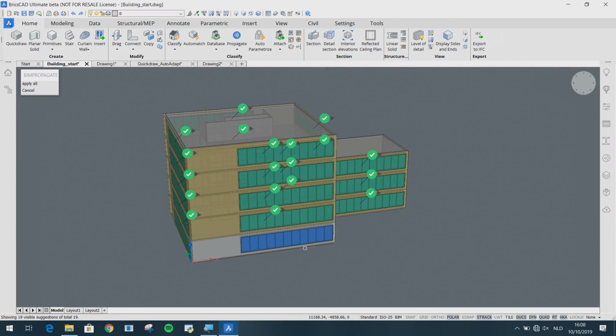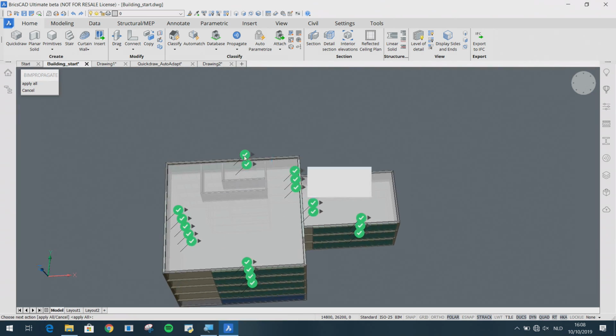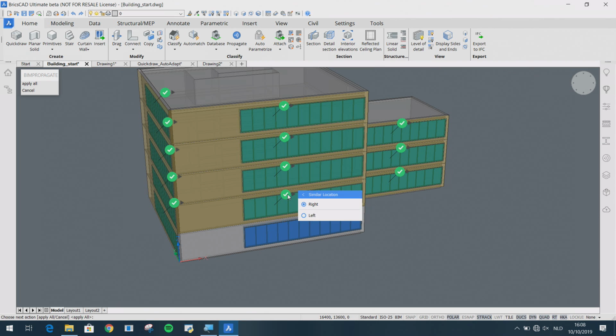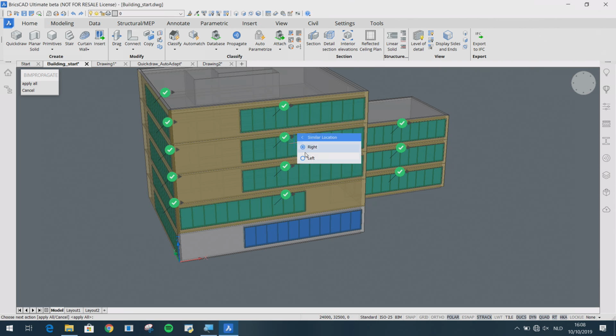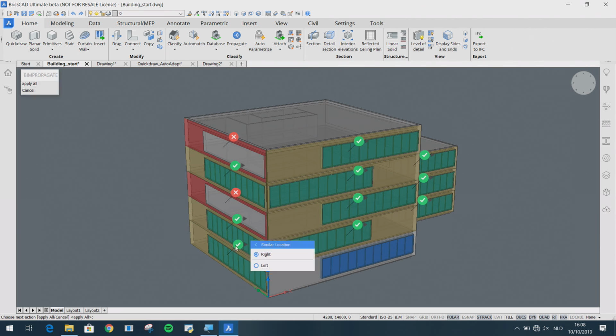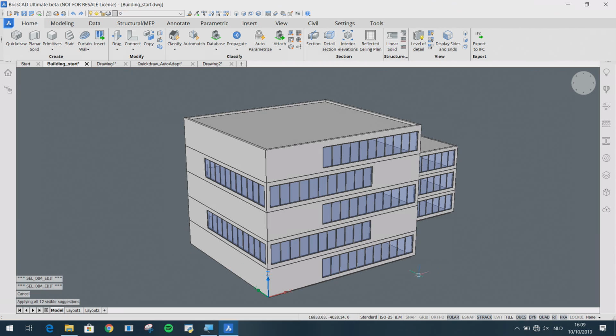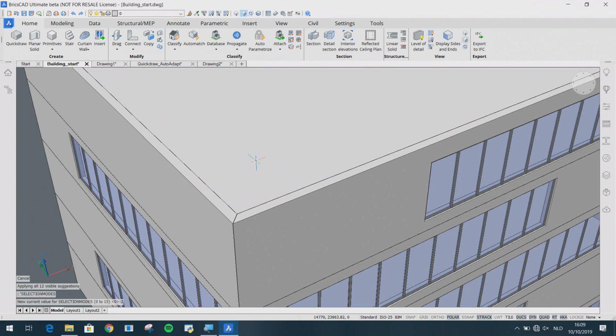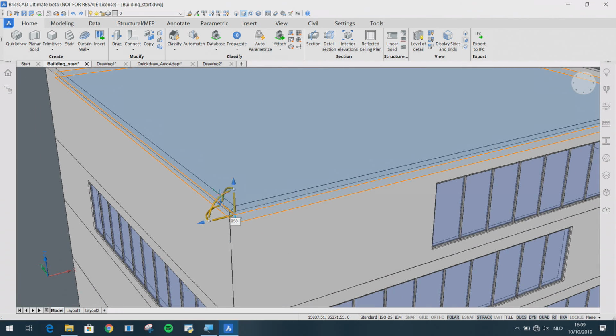But if you need this kind of repetition, you should try to consider using Propagate for this, even in this conceptual design phase. So that's what Walter is doing now. Quickly he propagates the window as a detail attached to a wall, and then by selecting which suggestions he accepts, which not, and by choosing some other options offered by Propagate, he quickly makes an interesting window pattern for this building. So, just to finish it off, we will add some slope to the roof.